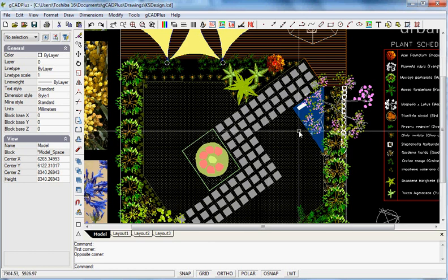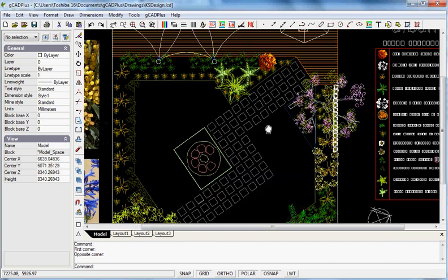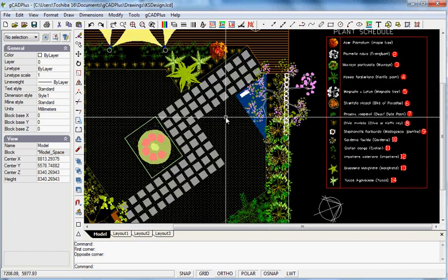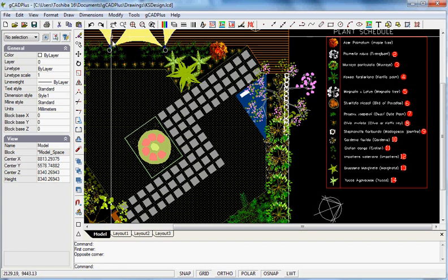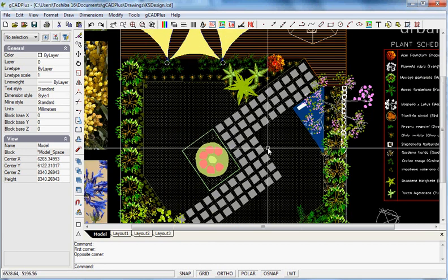It's not that hard. To move the drawing as though you were putting your hand on the desk and moving, hold the wheel down and you'll see a hand symbol appear, and you can just move the drawing from one position to another. All of these tools are available on toolbars. There's the hand tool up there, and there's the Zoom real-time tool and the Zoom Extents and Window and Zoom Previous, so we can go to where we were previously there. So practice those zooming techniques.